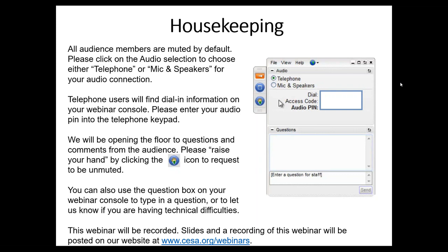So again, it all depends on your use case. So why would you want that? Well, if you're doing frequency regulation, you would want that. A quote-unquote slower battery, a C over 2 or slower, is great for these resiliency type projects that we're talking about. I hope that helps.